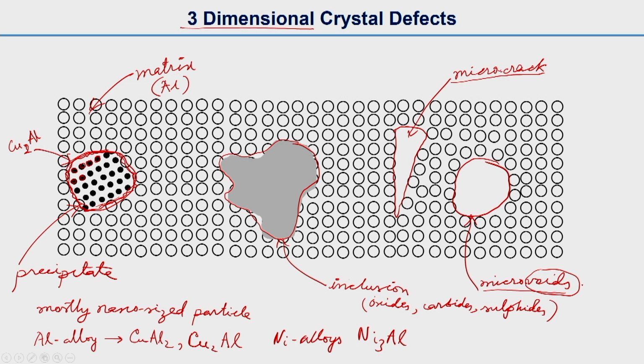Individual voids also grow during plastic deformation, and many voids come together and join each other. First it nucleates, then it grows, and then it comes together, that is called coalescence. That way the ductile material fails. I will just write that this is related to ductile fracture. That means the voids are responsible for ductile fracture, or failure of ductile material.